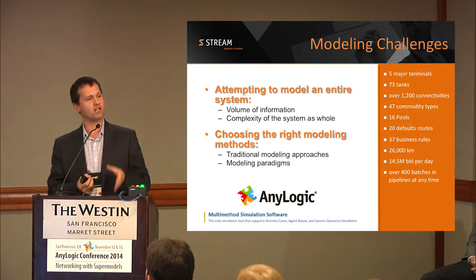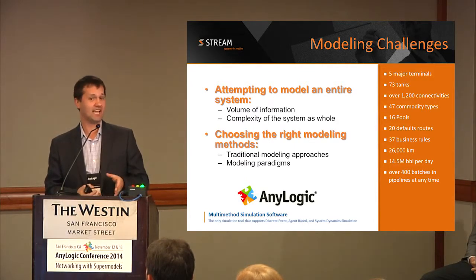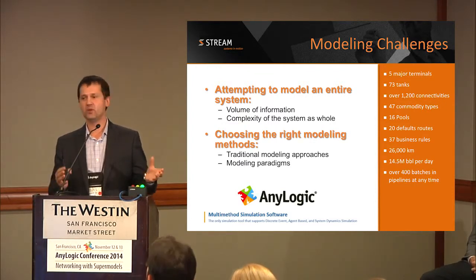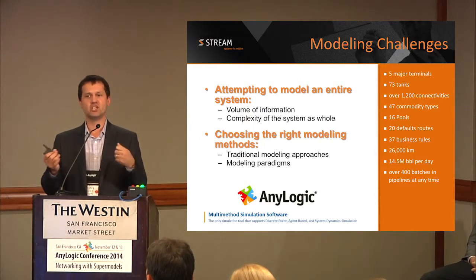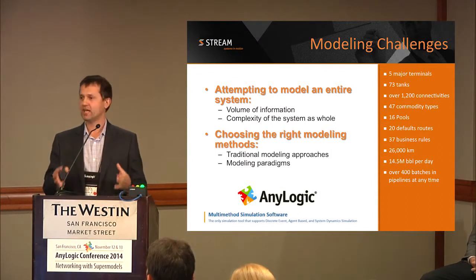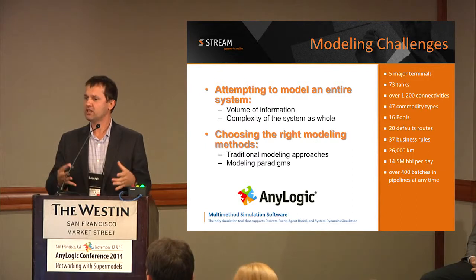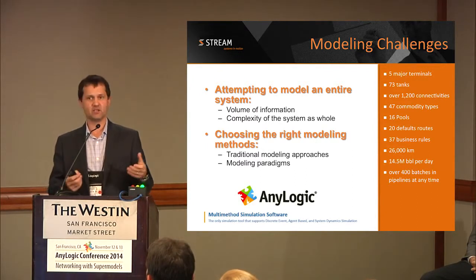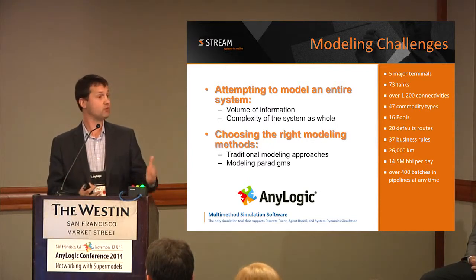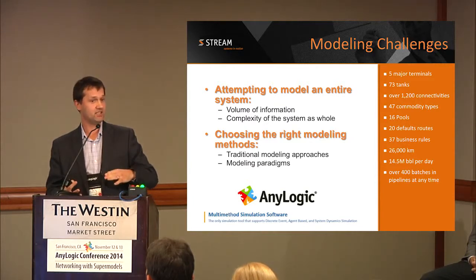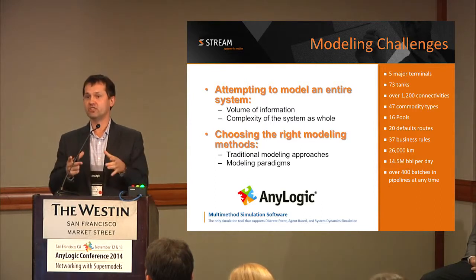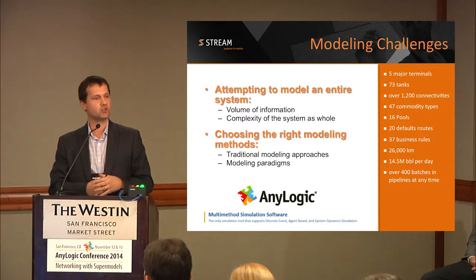Because when you have a 5,000-mile pipeline, it goes through at least 10 states, and the temperature can go from -60 to +60. Your volumes change dramatically. And if you have a little bit of a degree in engineering, like structural engineering, you will also understand that the pipeline itself, because you have over 2,000 psi, almost like your car washer pressure, inside the pipeline, and when it goes over a mountain, it goes to 10,000 psi. That's why your pipeline is actually breathing, and the diameter can change 2 to 4 inches. And as a result, your volumes change.